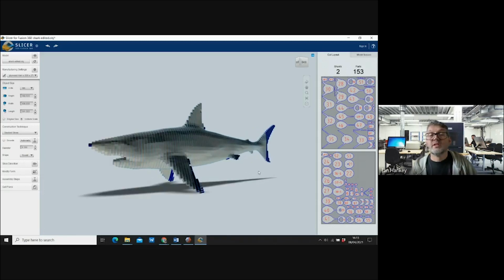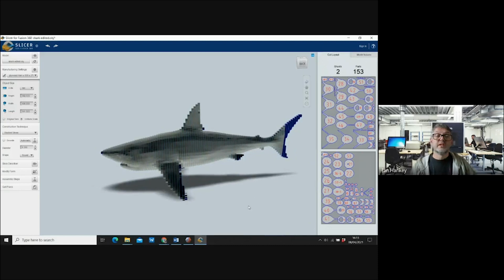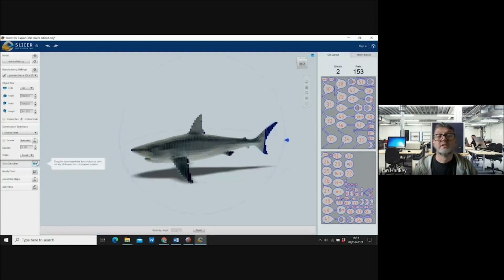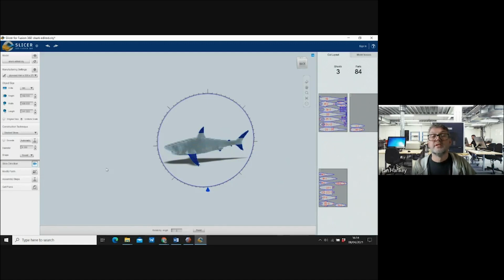So as you can see, our interlocking slices will be on 2 sheets at the moment because it's sliced through the shark, which is fair enough. If we change the direction of that, slice direction, and I'm going to highlight it by clicking first, and then just take that down to the 90 degree. And now we can see we're on 3 sheets, but those 2 we know we can go onto there, and these are just sliced up this way.